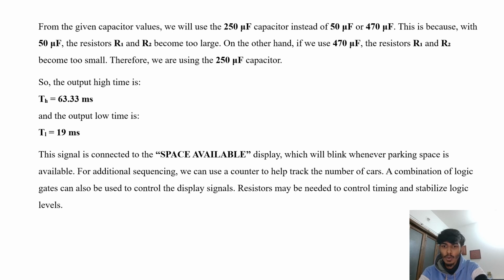In this slide, we choose 250 microfarad because it gives balanced resistor values. With 50 microfarad, the resistor becomes too large. With 470 microfarad, they become too small. So 250 microfarad gives the most practical circuit design.